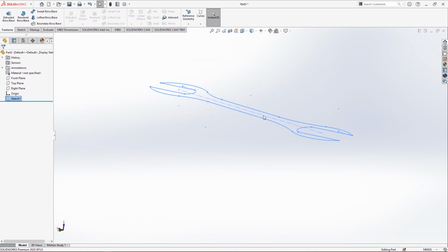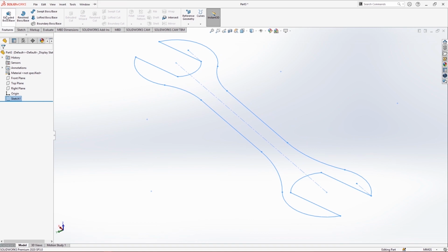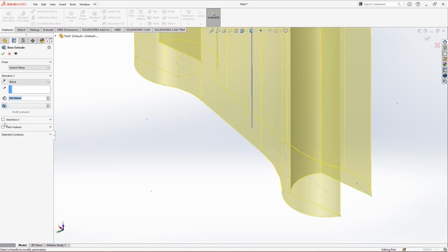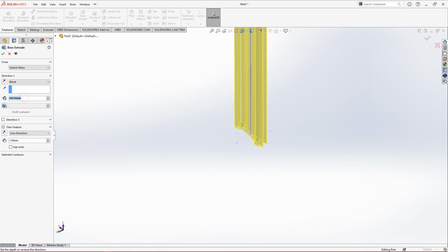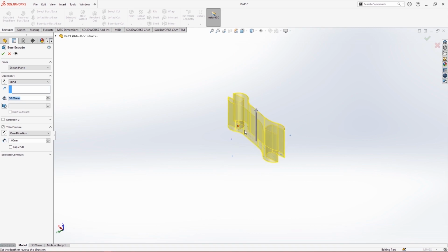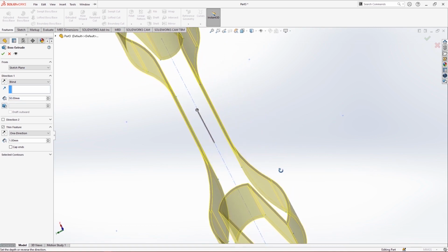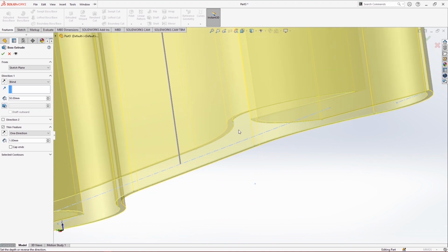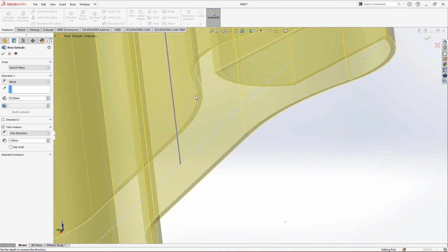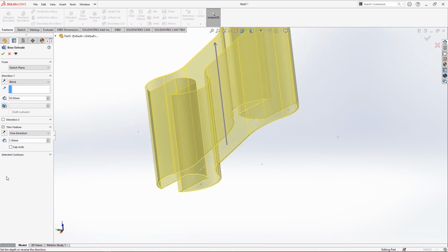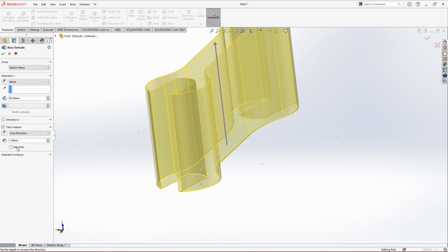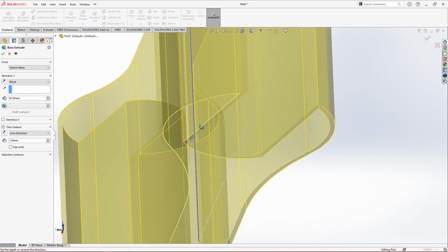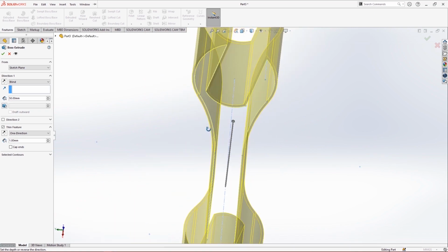Now let's discuss another feature, which is the thin feature. Let me decrease it to like 50. So you can see it's a hollow structure. What it does, it takes the particular curve and takes an outside curve length of 1 mm and extrudes it, and that is it. And when we click on cap ends, it actually closes the curve, otherwise it's hollow, you can see.